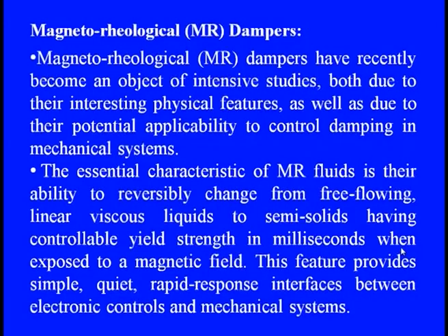Because the essential characteristic of MR fluids is their ability to reversibly change from a free-flowing linear viscous liquid to a semi-solid, with a controllable yield strength in milliseconds. When exposed to a magnetic field, the yield strength can be clearly controlled even within a fraction of a millisecond.